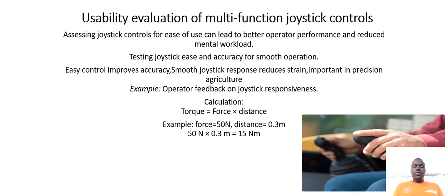Example, we have a force of 15 newtons and a distance of 0.3 meter. To calculate the torque, we take 15 newtons times 0.3 meter.